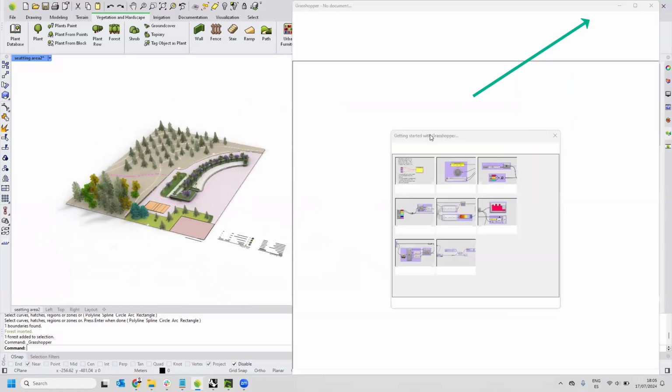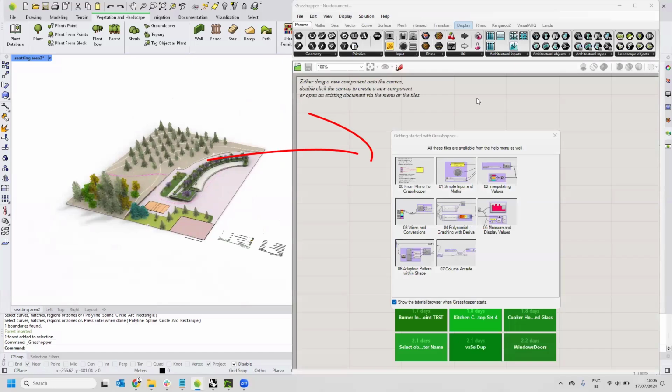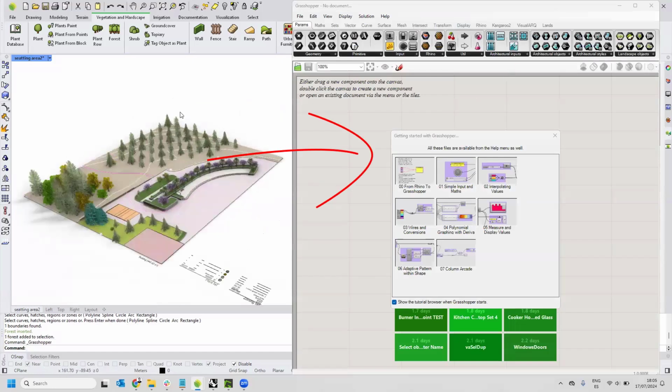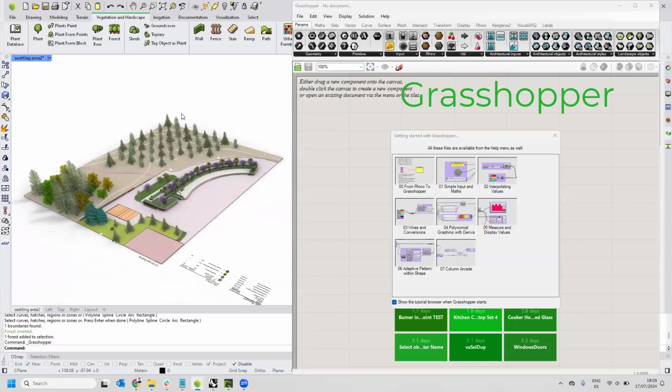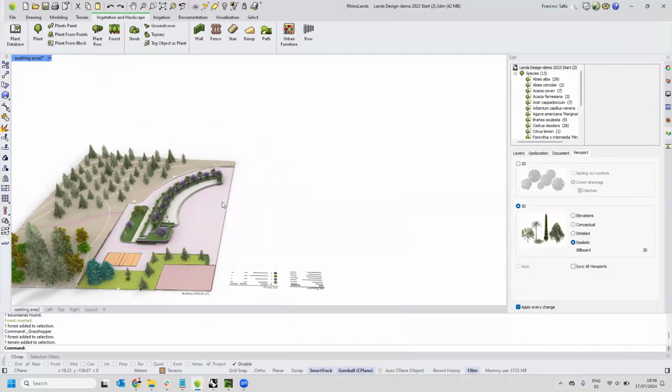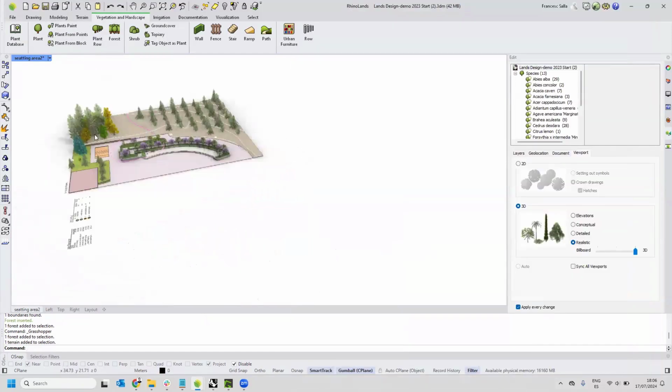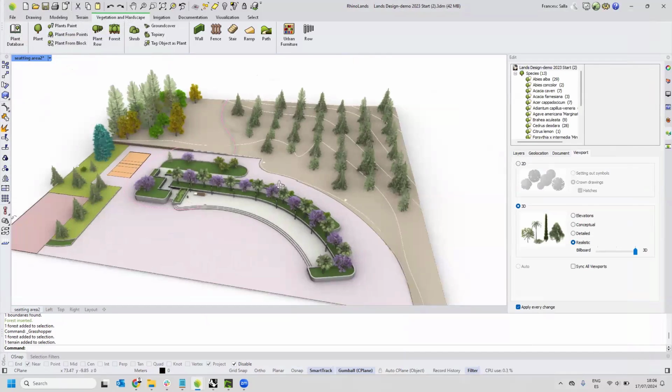Exactly. I mean, you run Grasshopper, you have Ladybug tools, and you can link the 3D model with these tools to do more detailed environment analysis. Actually, you can reference all these elements in Grasshopper, and the plants can be exploded into meshes. So with the resulting geometry, the resulting meshes, you can do whatever you want with Grasshopper. Same for the terrain. It's nothing but a mesh, but you can use this mesh to run any analysis that you like.